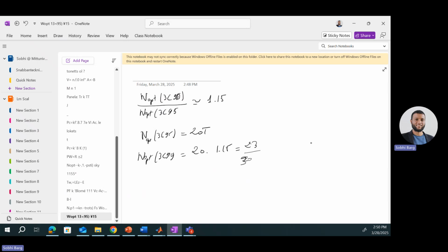And if you increase by one more layer, then the AC resistance will increase exponentially. If you look at the Dowell equation that calculates the AC resistance, you will see the effect of the number of layers. If you increase the number of layers, the AC resistance will increase exponentially, and the winding losses will do so. And this will increase the temperature of your transformer.